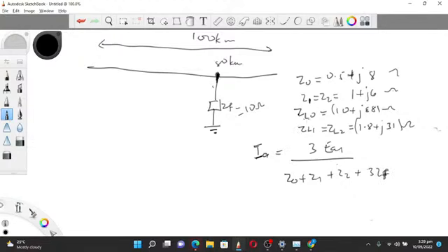Now you know that. Okay, this is the general formula. Don't say my Z0 here is not the Z0 here. I'm just writing a general formula for you. Now if I want zero sequence impedance, you can see that there's a zero sequence impedance here, there's another zero sequence impedance, right?